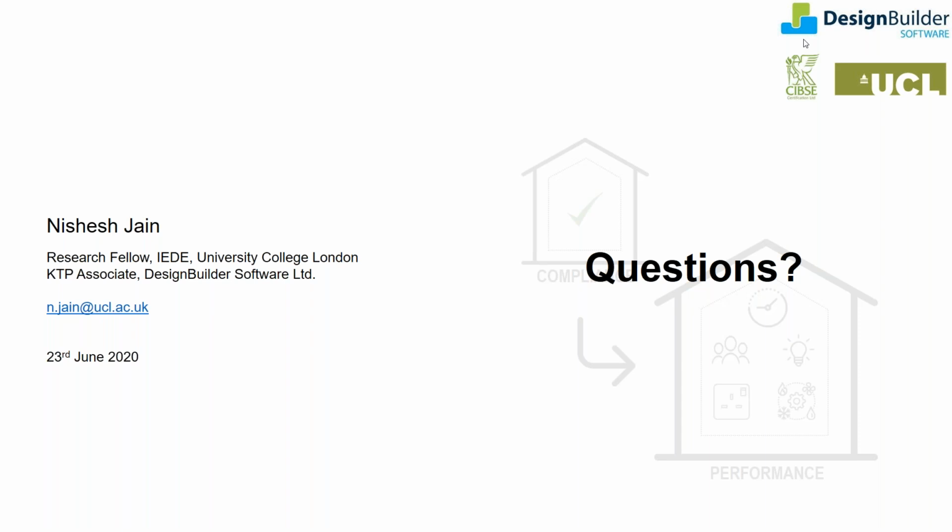And the second part was how it relates to the performance modeling I am discussing now. When you create a TM54 sort of model, you'll be doing it at a design stage, and then when the building is operational, you would like to compare what your TM54 calculations predicted against what is happening in the building. So you can compare the TM54 against actual. But if you want to analyze the reason why there's a difference between TM54 and the actual, that is where calibration comes in, calibration using proper methods.